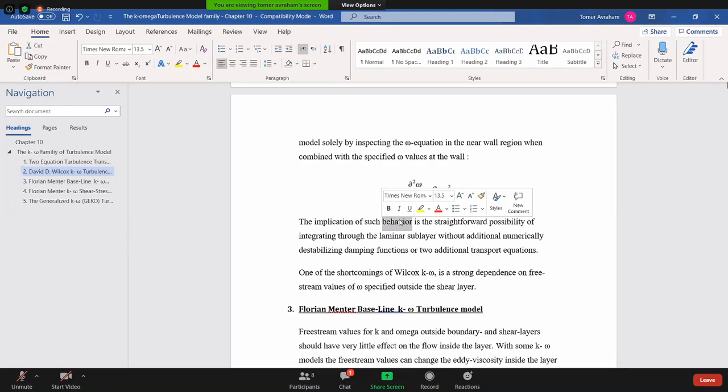As Pollard said, we wouldn't be able to do a complete airplane with large eddy simulation at least until 2017. We have other methods which are called hybrid methods, like detached eddy simulation, where we switch between Reynolds-averaged Navier-Stokes near the wall, and then large eddy simulation all over away from the wall.